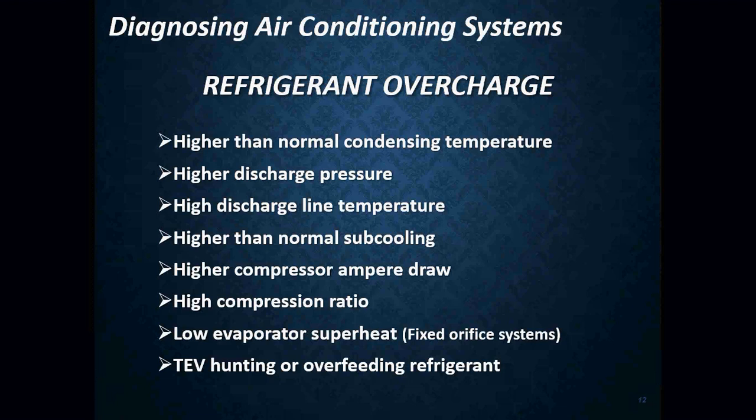Okay? With a 10% overcharge, liquid may enter the suction line and reach the suction valves or crankcase inside the compressor, and it can damage or cause the compressor to fail. So we have to make sure, again, that we are checking what we're seeing. Okay? Rule of thumb, when in doubt, check it out. Okay? Take some additional readings to see what is going on. Take that extra 5 minutes.